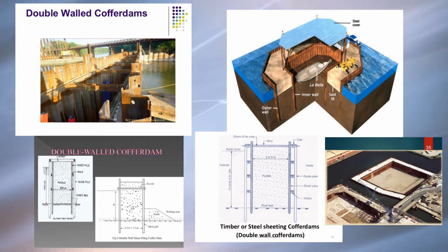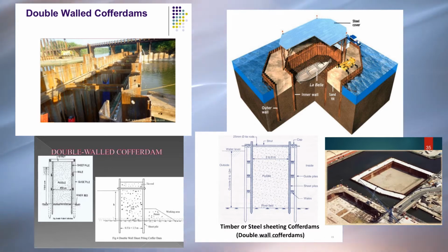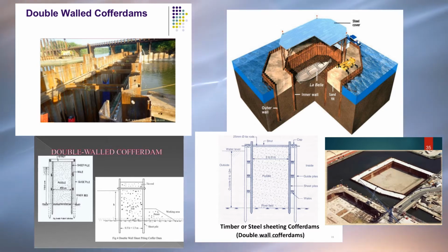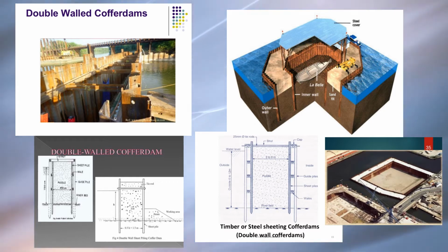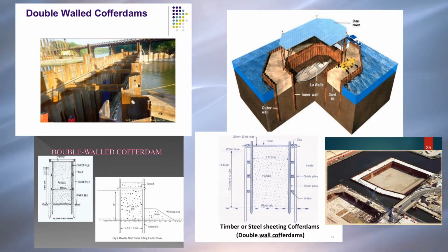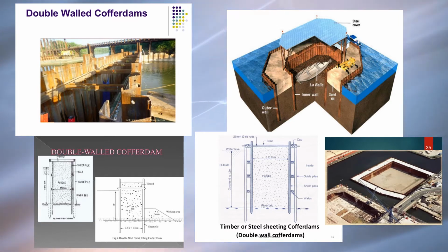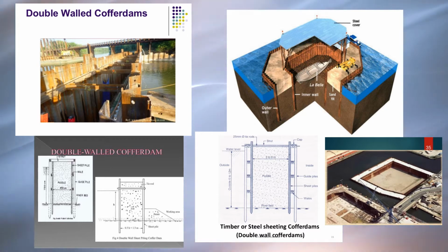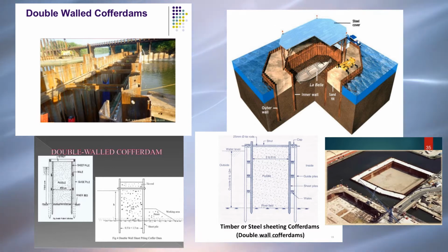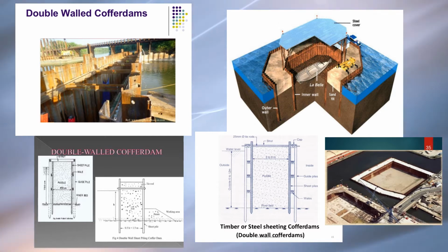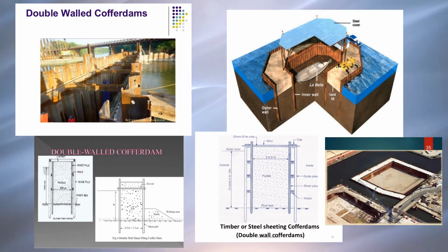When the excavation area is too wide for a single wall cofferdam, then a more massive cofferdam can be constructed by utilizing a double layer of sheet pile walls. The sheet pile walls are tied together or can be formed into interlocked cellular cells filled with rock debris or earth infill between the sheet pile walls. This forms a massive self-supporting cofferdam that can keep exterior water at bay and the working area dry for construction works.